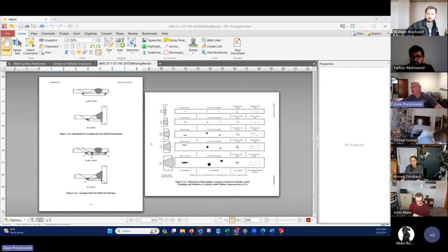When you use a universally fully welded note, how much are we specifying we're leaving out? We're trying to kind of leave it to them to do their job because it's not really, I'll call it structural, right? 200 pounds, I don't need much on that pipe weld to hold it, right? So by the time they seal it all up and caulk it, that should be enough.